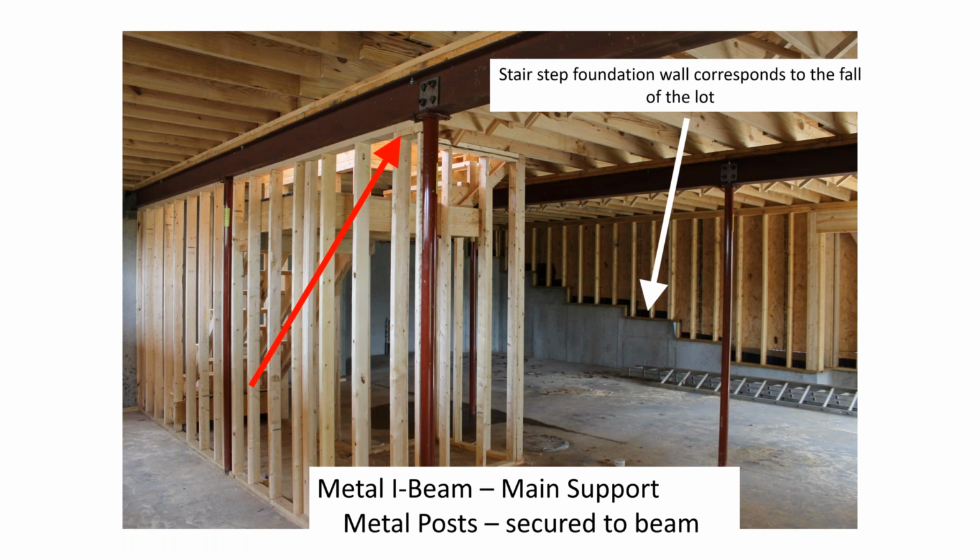So in this particular house, there are 2 I-beams running parallel with one another, and then you have this post right here, which is designated every so often to sit on top of that footer. So there's going to be a footer directly underneath this post, a footer directly underneath this post, and then one back here, and then it's going to sit on the exterior wall up on the ground level.